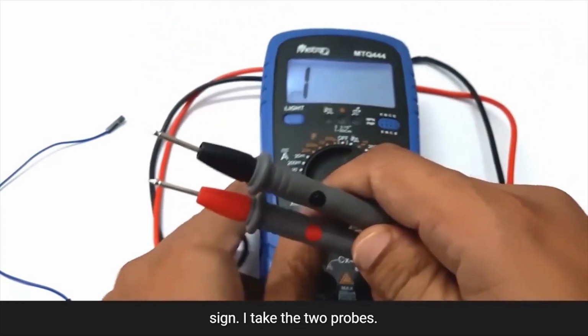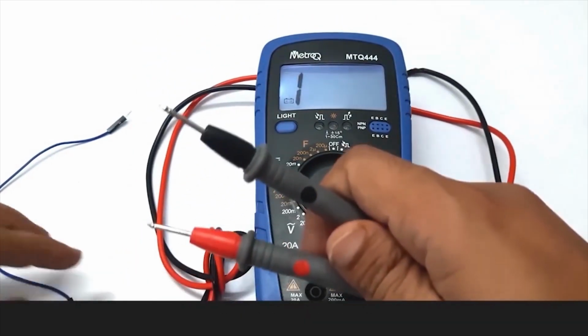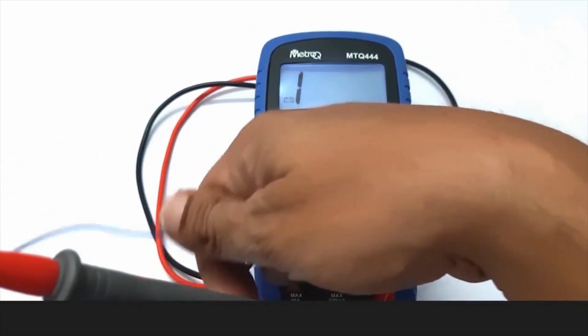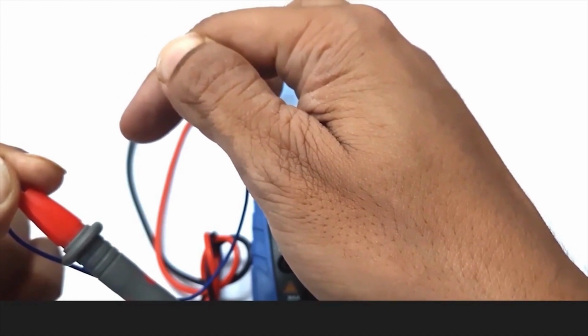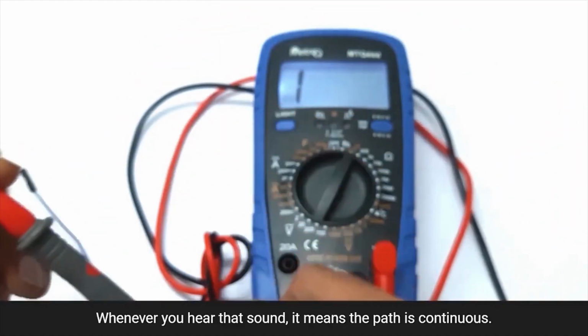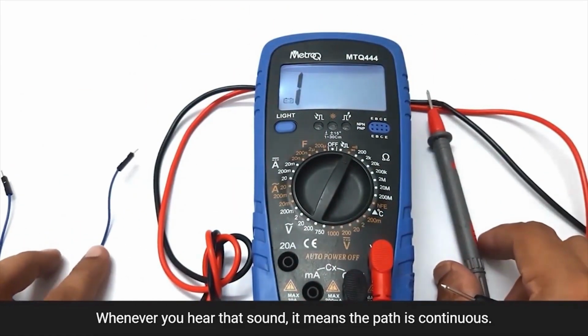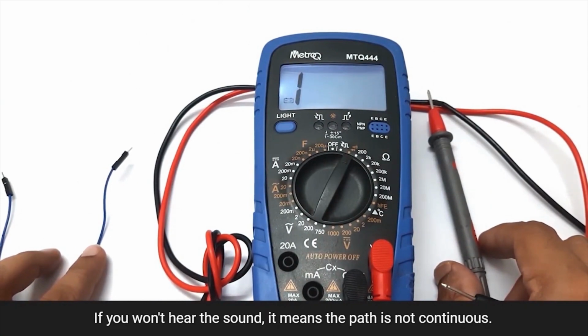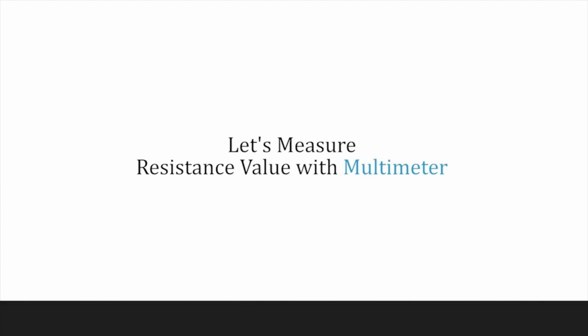Now take the two probes and connect them to the two terminals of the circuit or a wire. So you can hear a sound. Whenever you hear that sound, it means the path is continuous. If you don't hear the sound, it means the path is not continuous.